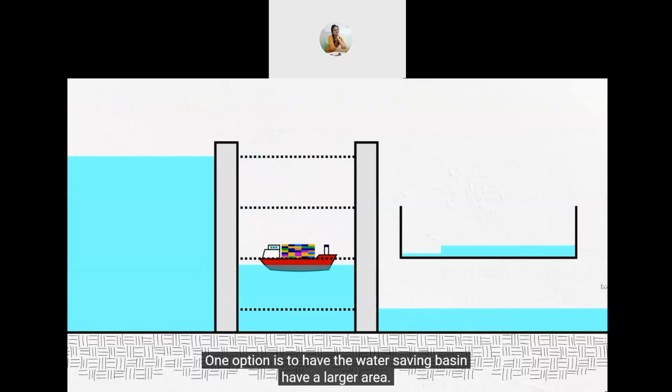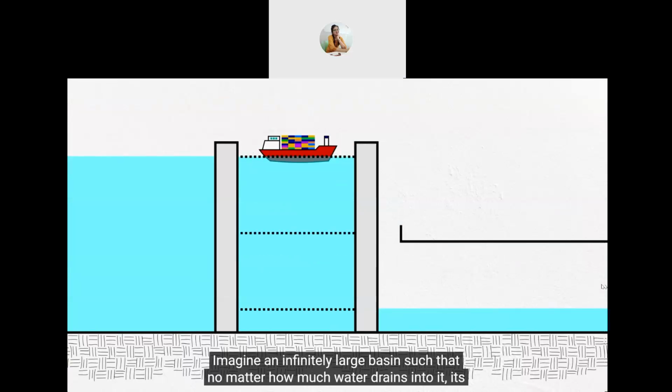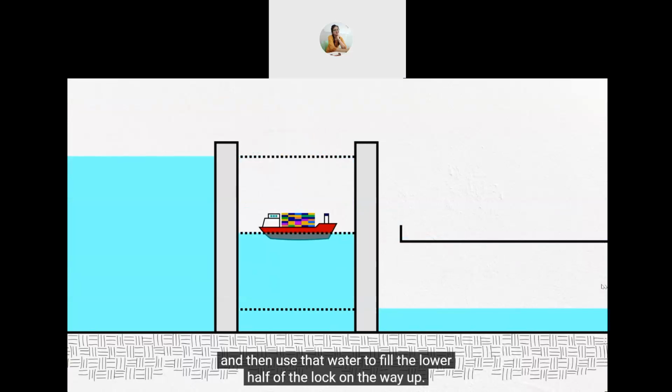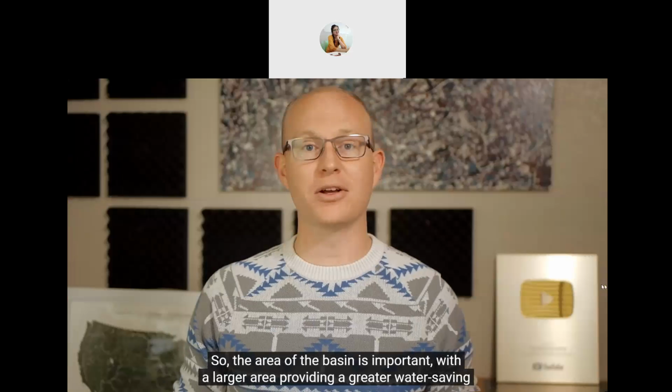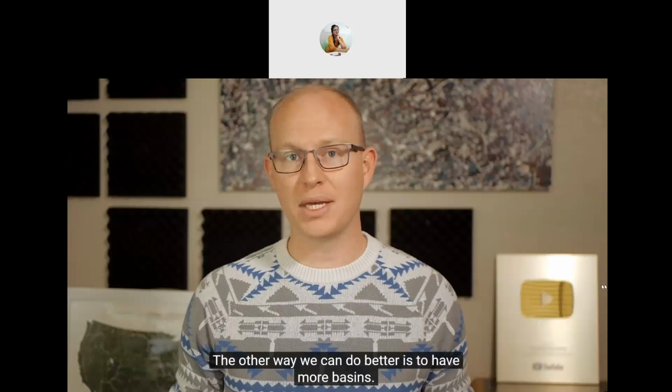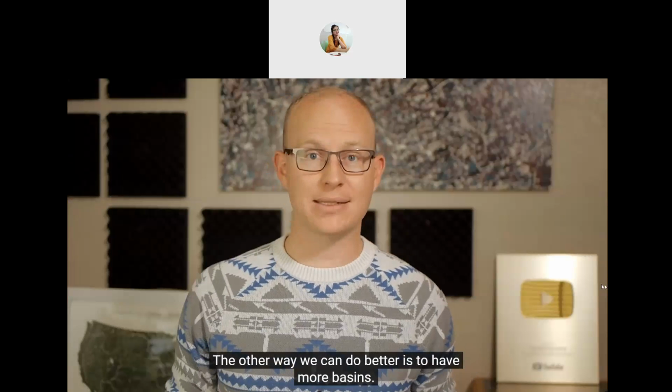One option is to have the water-saving basins have a larger area. Imagine an infinitely large basin so that no matter how much water drains into it, its level never rises. In this case, you could drain the upper half of the volume of the lock into the side pond, and then use that water to fill the lower half of the lock on the way up. So the area of the basin is important, with the larger area providing a greater water-saving benefit. The other way we can do better is to have more basins.